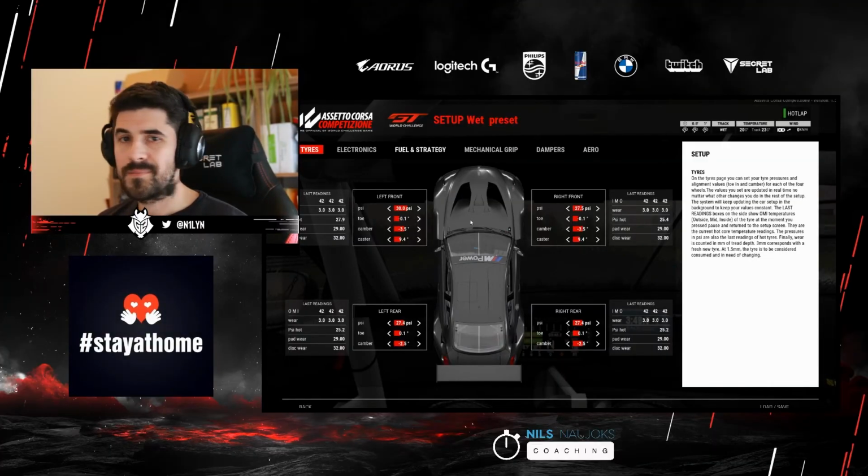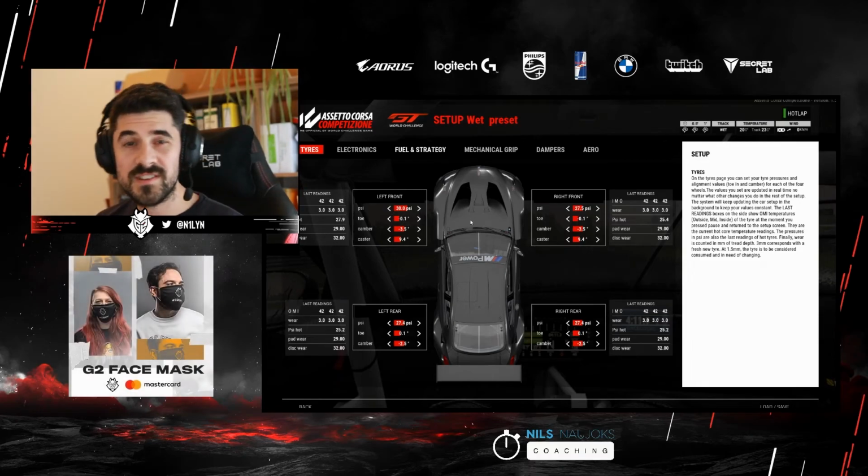So by design, the wet tire creates temperature still in wet conditions because it generates grip there, and for that reason also generates heat, which means for the rain tire in the rain, it will also start generating higher pressures as you drive along, especially when the weather is kind of in between and the wet tire just started to become the optimal, or you're slightly early into the pits because you know the weather is going to change further and the wet tire will be optimum in a couple of laps, but you're pitting now and you don't want to pit again, then you probably end up with a wet tire that is kind of still not optimal because the track is too dry.